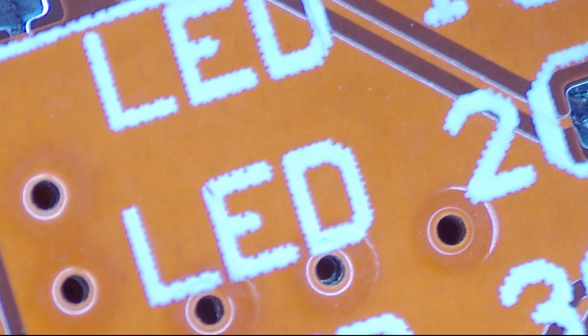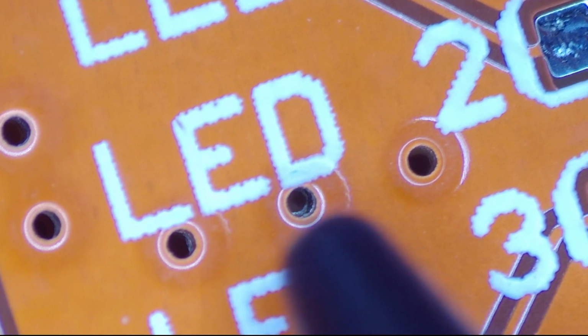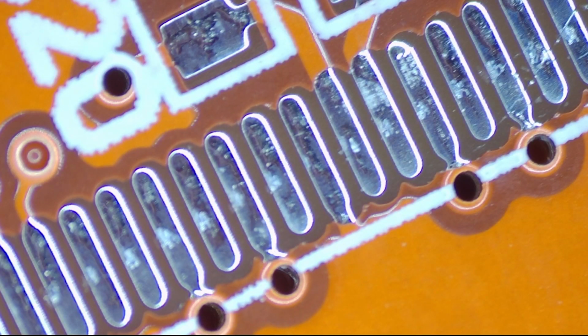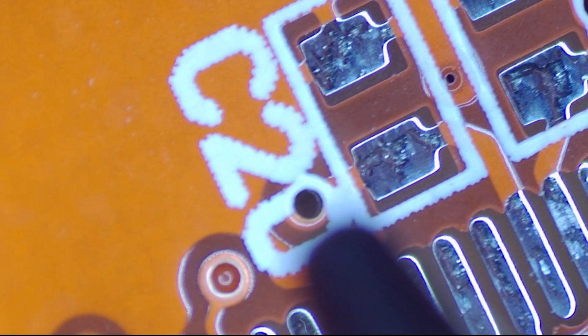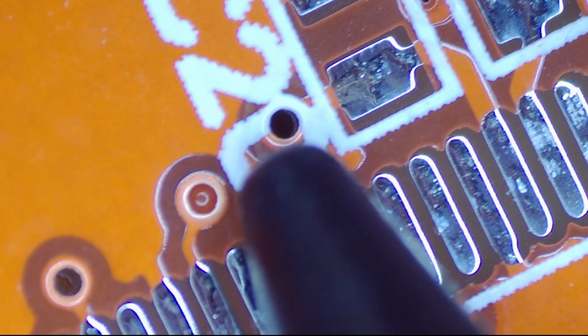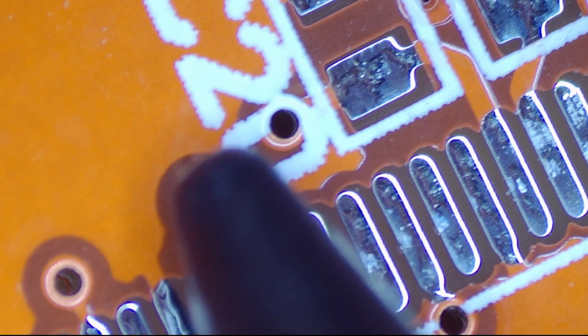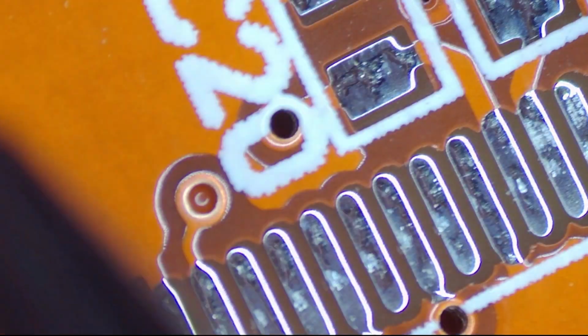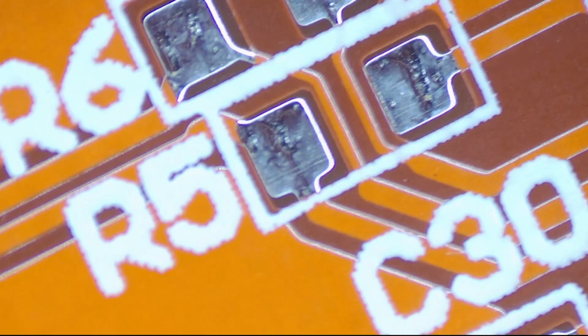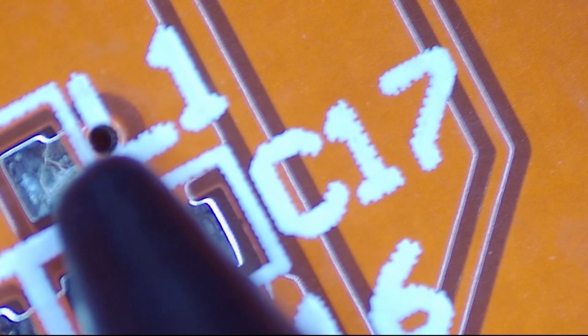So let me see if I can find a spot here with a via. Right here you can see just the edge of this LED text, right? It's over top of what would be the via pad. If I didn't tent that, the manufacturer would be cutting back my text. So often we want lots of silkscreen text to be unbroken, and so we want tenting. Here you can see, for example, the silkscreen text has actually gone in the hole as well, right? What would happen if I wasn't tented is it would be cut back to the exposed copper, so it would be cut back even more. So the tenting depends on your via drill size. Here my drill is big enough that basically the solder mask is falling through.